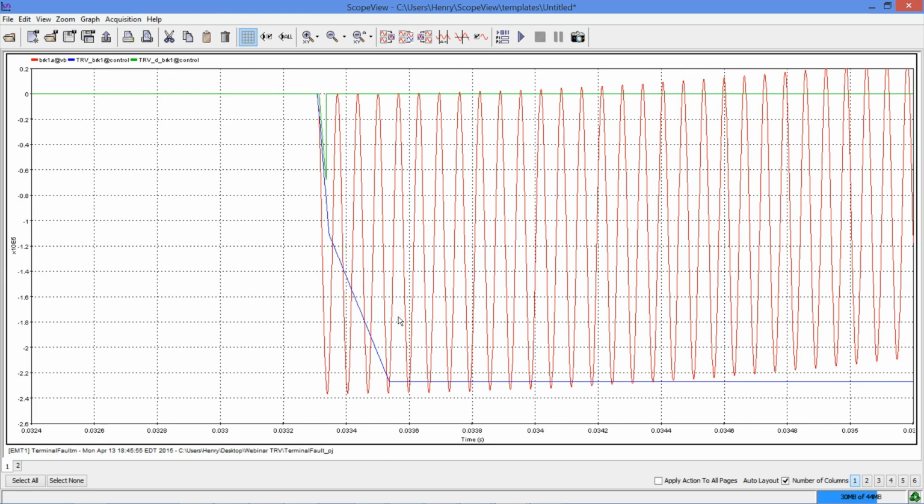It's also possible with EMTP to simulate the reignition. For that we can take the exact same block we had and compare this voltage with this one, and use a control gap and close the control gap as soon as the voltage reaches the limit. It's kind of a cheap model, but a pretty good one to simulate the reignition. If you want more information about that, you can contact me as well. I can send you some model. And the best here is, of course, to model the arc, and in that case, it's the most precise.